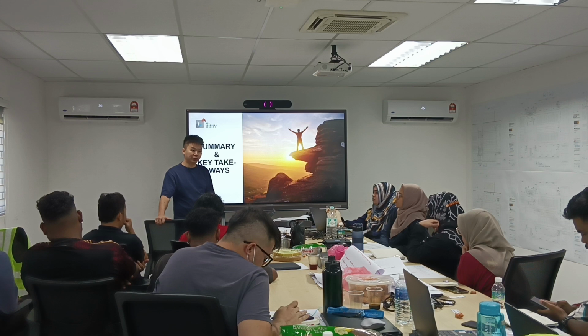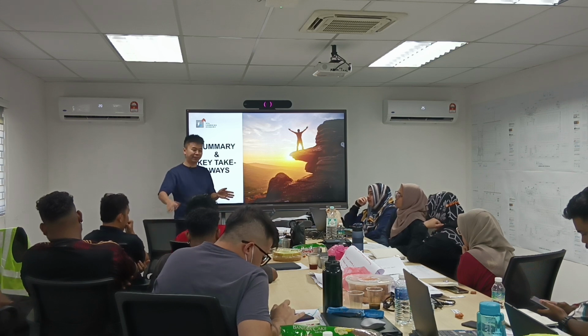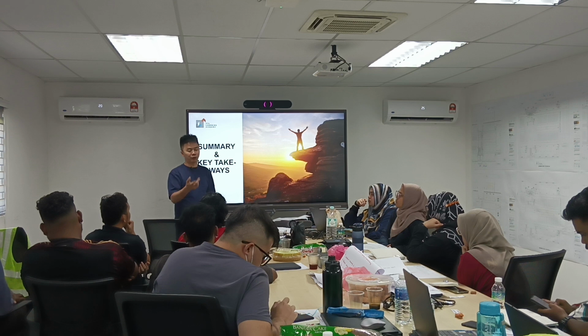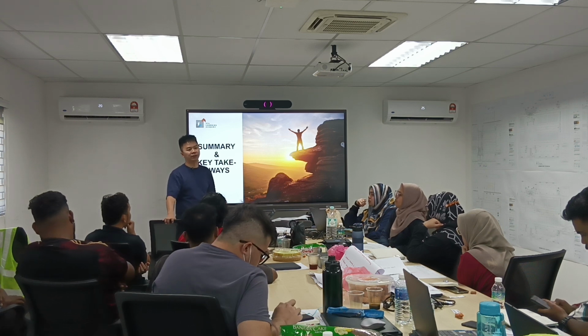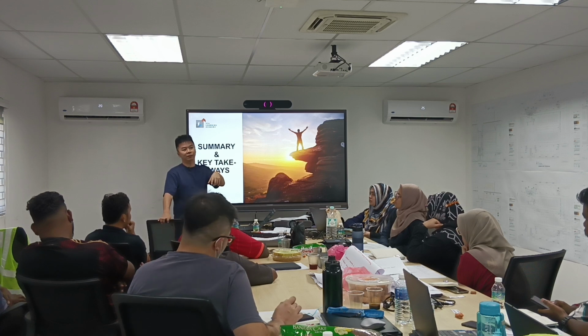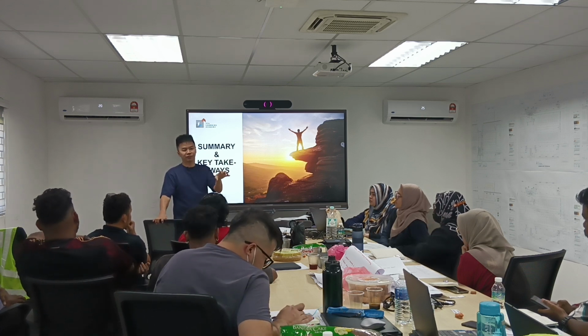Okay, so more than tolerance, what I suggest you do is this: the shop drawing has been approved, but now the site does not tally with the shop drawing. Two choices. First choice, ask the contractor to adjust the equipment to suit back the shop drawing. If it can't be done, or the contractor doesn't want to do it, the second choice, which is a choice I don't want to make, is to ask him to revise his shop drawing and get approval again. But this is stupid. The moment you start this process, your construction philosophy is totally wrong.